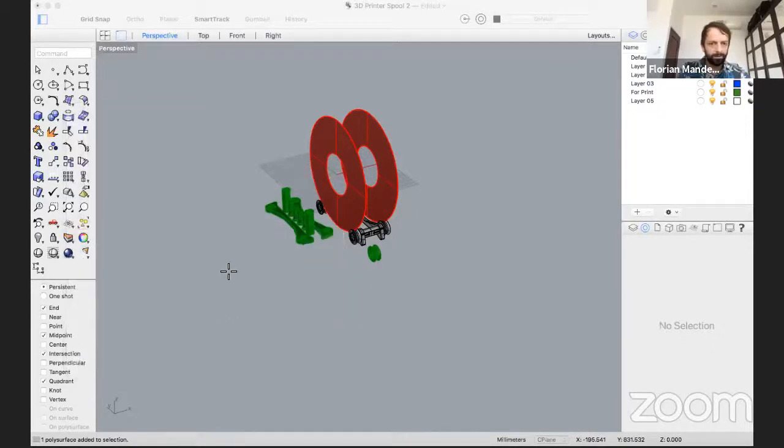And that's where I need the side view, because from the top view I can't really see what I'm doing. But from the side view, front or right, I can adjust the height. I can type it in, say 10 millimeter, 20, or I can select it on the grid. And then I can see in the perspective that I created a 3D shape.